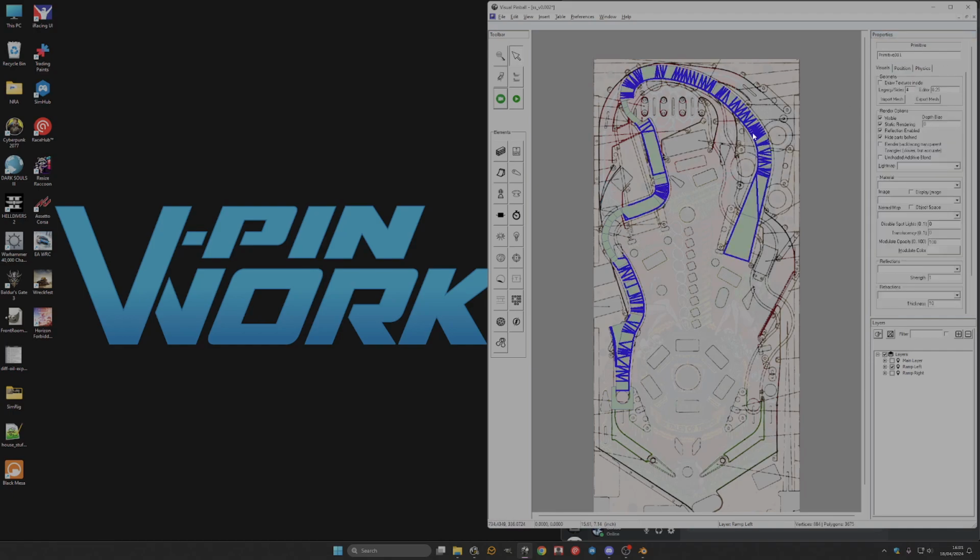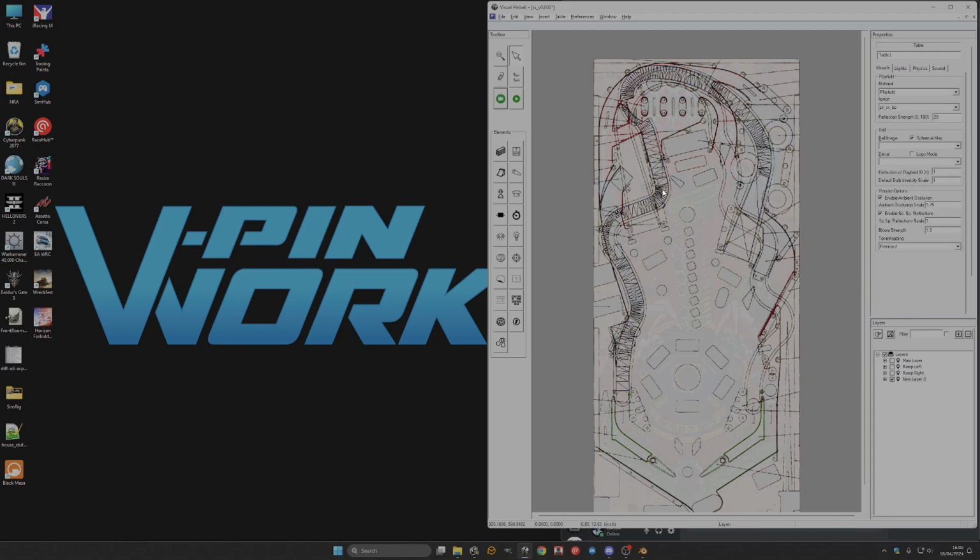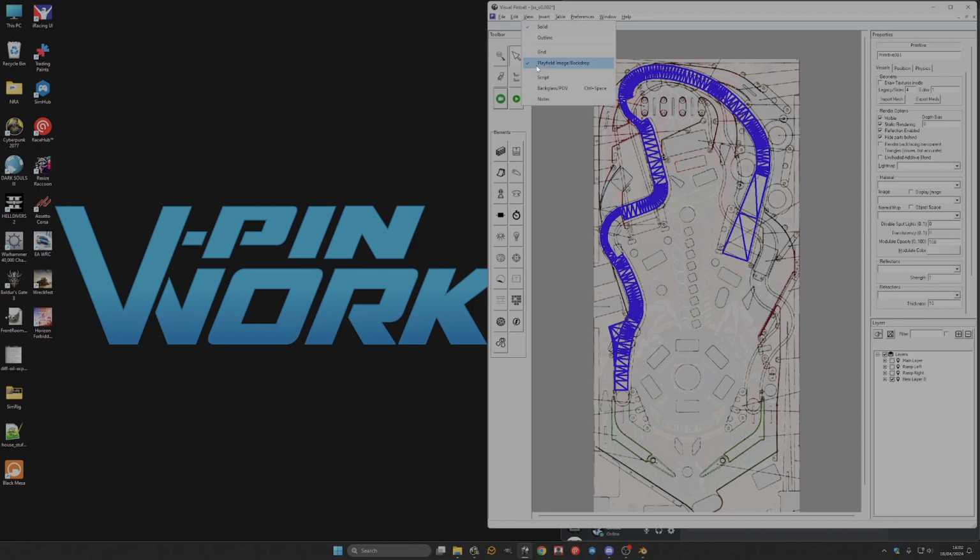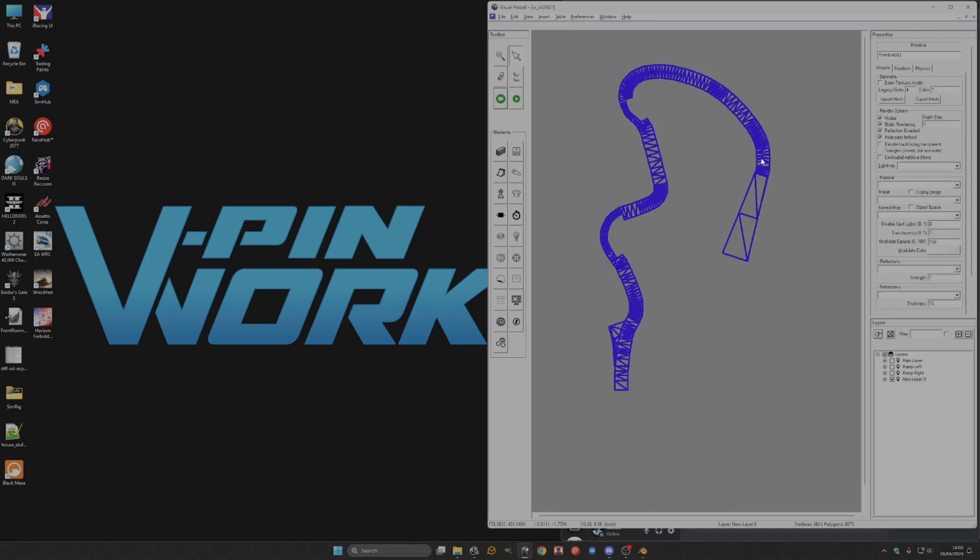If we click the ramp, at the moment, editor means how detailed it's showing you that object. We're going to create a new layer and put it on its own new layer. If we set this to 1, it's now fully detailed. And that is our primitive ramp.